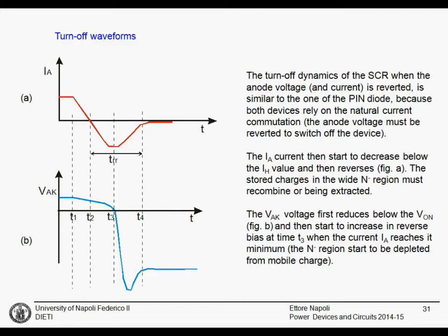Only after the device is completely on, it is safe to remove the gate pulse and bring to 0 the gate current. And the device will stay on. Otherwise, you risk that the device will switch off again.